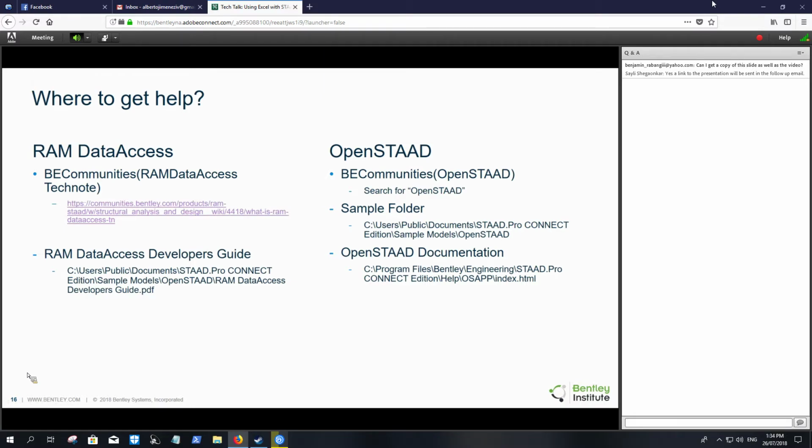Thanks, Renchal. The second question came in: STAAD file syntax related to this create model, modify model? Oh, right. Yes. For some more experienced STAAD Pro users, you may have interacted with STAAD Pro by directly modifying or writing the STAAD Pro file, and they have these keywords, joint coordinates or members.